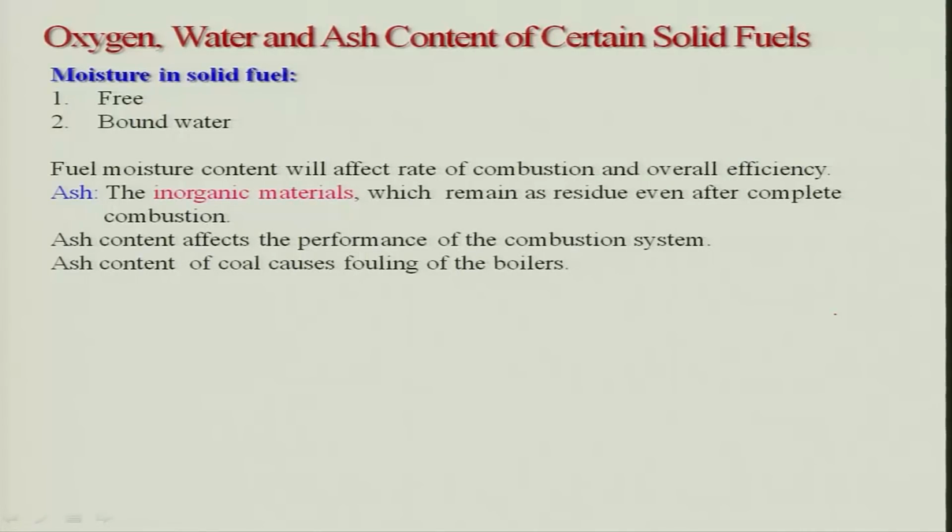So therefore this cannot be burnt; you are just carrying a piggyback on your shoulder, like as a fuel. So therefore it is wastage. Ash content also affects the performance of the combustor, because it forms layers that act like insulation and absorb the heat, reducing combustion efficiency. Ash content of coal causes fouling of the boilers, and when it is emitted, it causes a lot of problems.